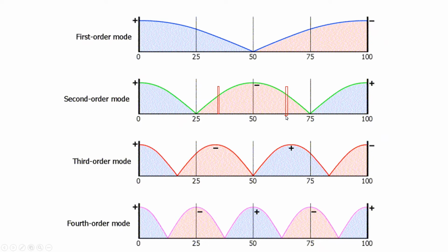Those 100 hertz bass is important, and you have a very good bass. The same here. But if you sit on a wall, you will have excessive bass. And excessive bass, of course, you can attenuate in an active speaker system, but also you will attenuate other frequencies about 300 hertz, where there is a low male vocal, and you will have a coloration. So it is better to sit with a neutral bass level.